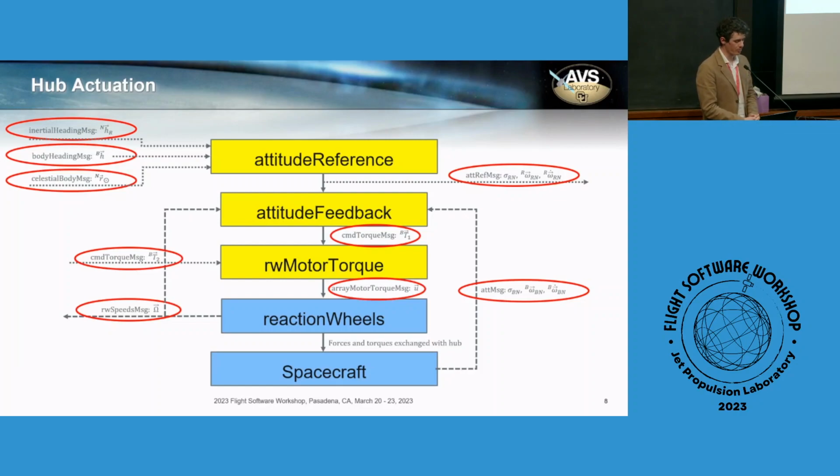Why do we have this other component of torque fed into this module? That is not strictly necessary. We could solve the problem without doing that, but the choice to do that is because if we did not provide this additional piece of information, the torque produced by the thruster on the system would effectively act as an unmodeled external torque, and it would have us rely more heavily on the integral term on the attitude feedback loop to achieve correct pointing.